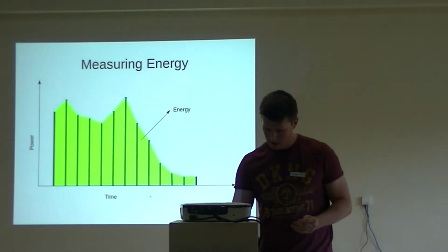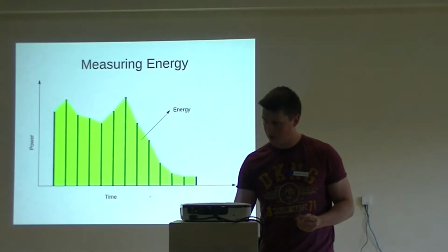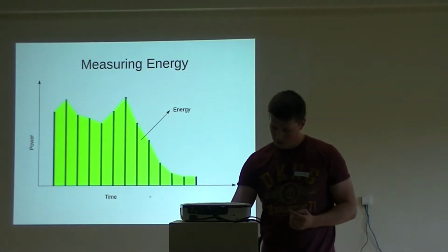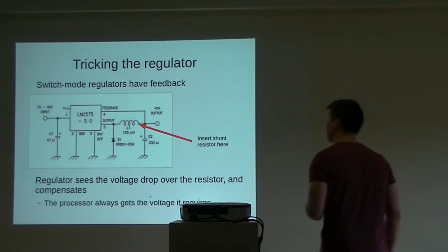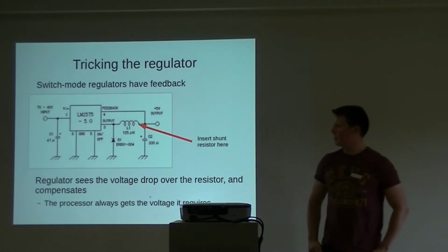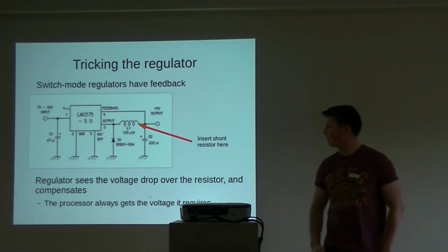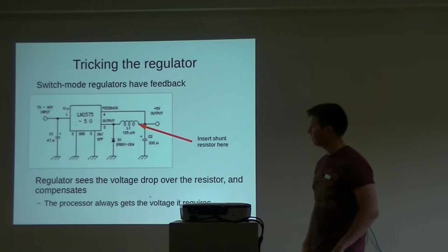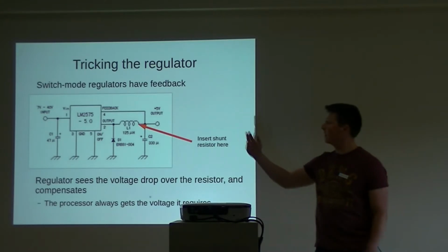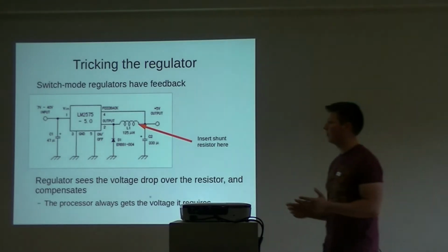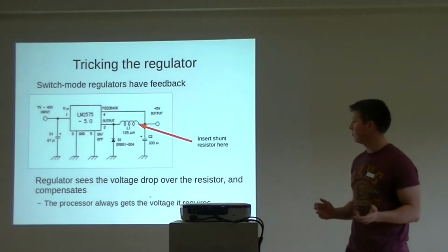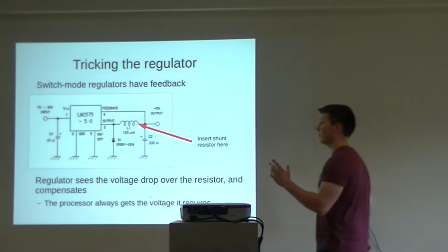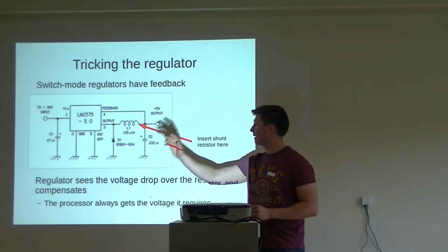So we've been attaching these probes to lots of different boards, and one trick we've found is this switch mode regulator is on lots of high-end boards. So the Beaglebone has got some regulators which look like this, and these regulators work differently and work via feedback. So they've got a feedback line which allows them to alter their output voltage to make sure it's smooth and consistent. But this also means that we can trick the regulator essentially, put our shunt resistor in between here, between the feedback and the output.